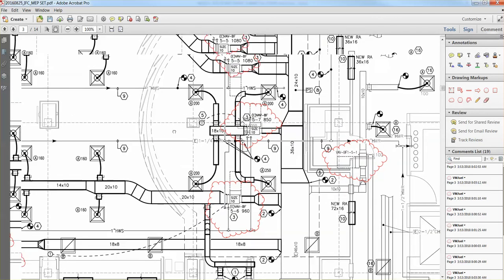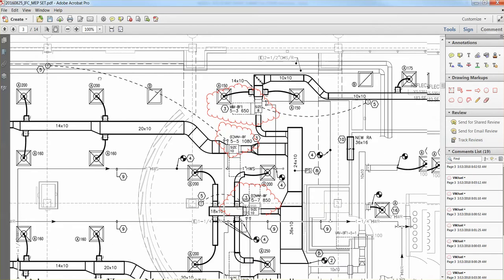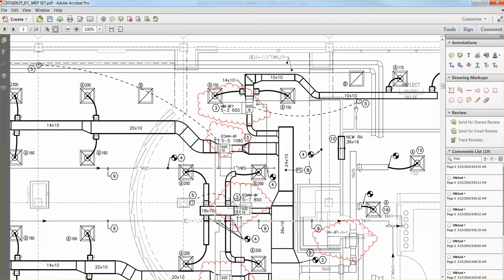When I actually did this, I did run into a problem. So we're crystal clear on this, for this air terminal, the room number is where the thermostat is, not where the air terminal is located. So the room number reference is where the T-stat's located.